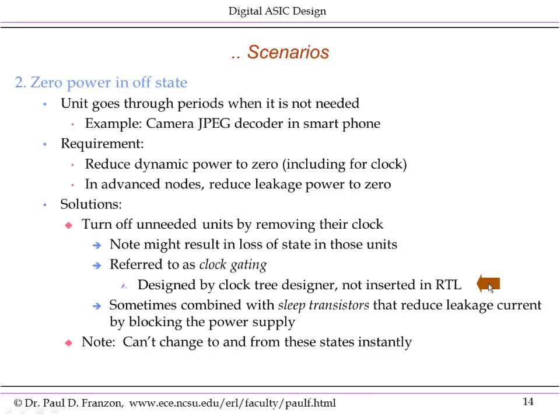If you, as the RTL designer, start willy-nilly sticking logic gates into your clocks, you are really screwing up the skew calculations that the timing tools have to do to make sure the chip works. And you're quite likely to get a failed part as a result. Clock is golden, you can't play with it. Clock gating is valuable; the clock designer does the clock gating.